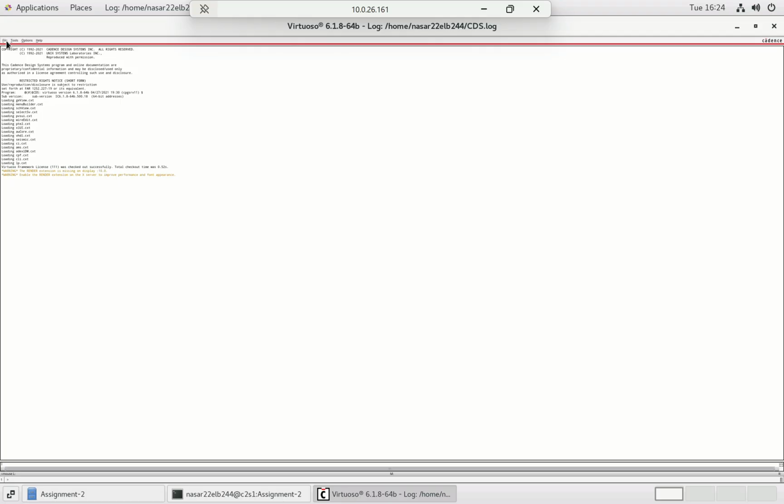A Schmitt Trigger is a special type of circuit that introduces hysteresis. That means it has two different threshold voltages, one for switching from low to high and another for switching from high to low. This prevents false triggering due to noise or slowly varying input signals. Basically, it converts a sine input wave to a digital output wave.